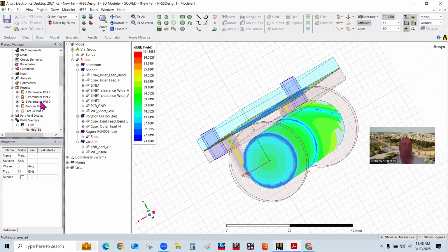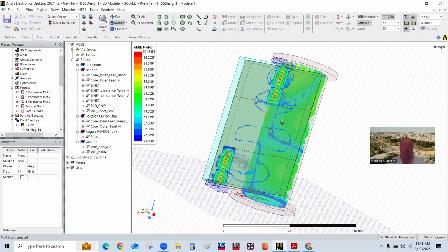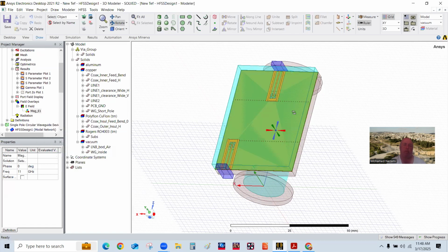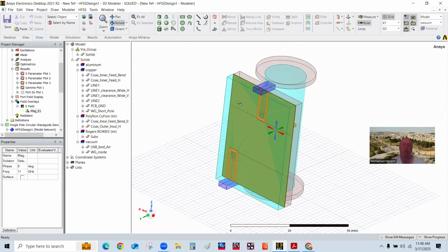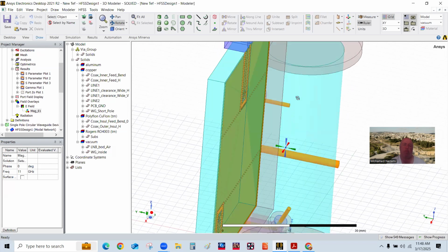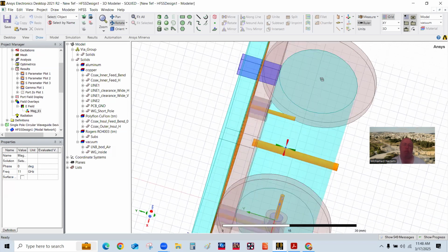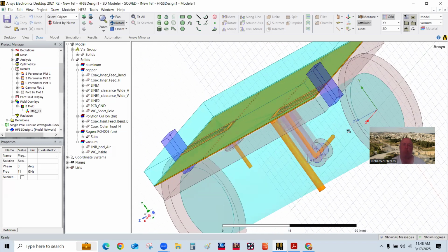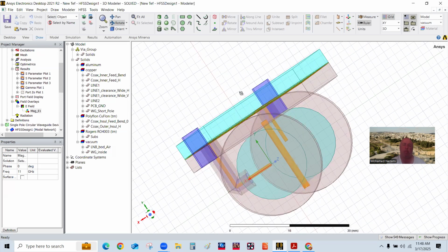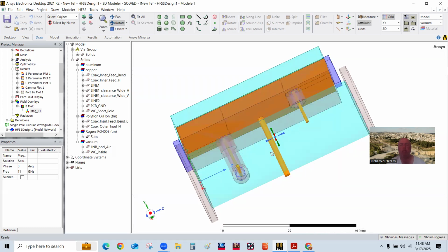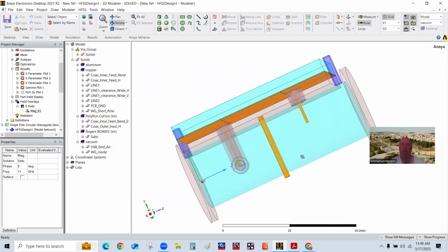Okay, so let's pick up today. Like I said, let's go back to last time. Last time we covered this here, and this was the one that uses two pins, one that penetrates down into the waveguide to pick up the vertical, and one that goes off the side and then has a 90-degree bend to pick up the horizontal component. And in the middle, of course, I had a metallic rod that acts as a backshort for the vertical polarization.